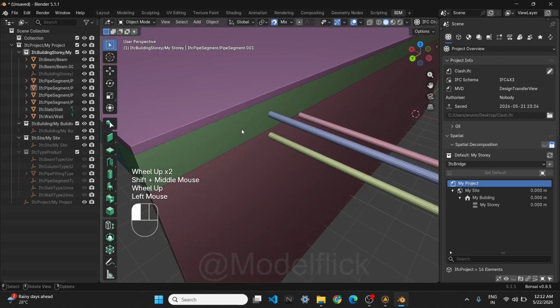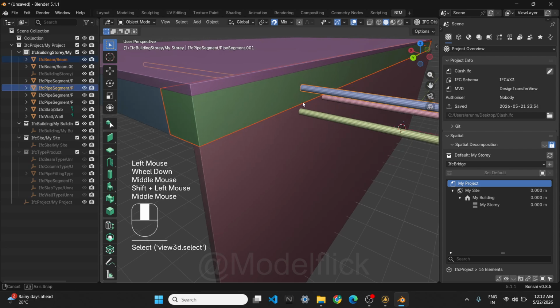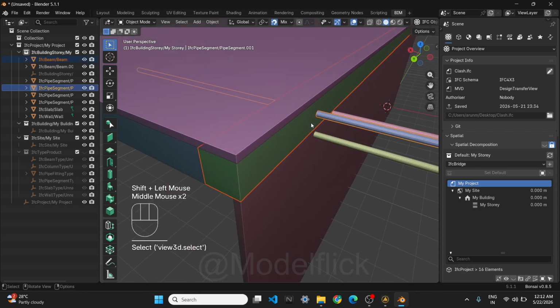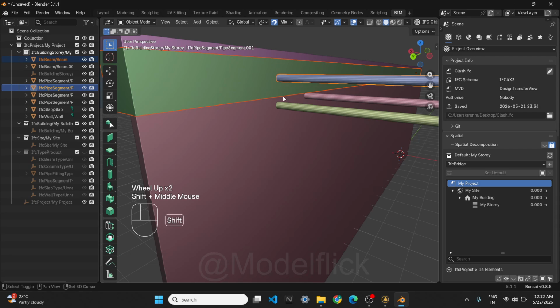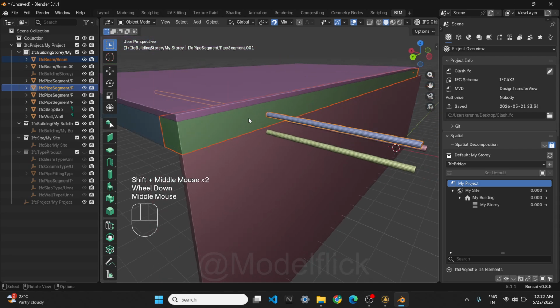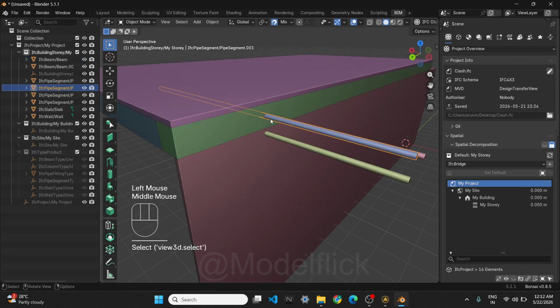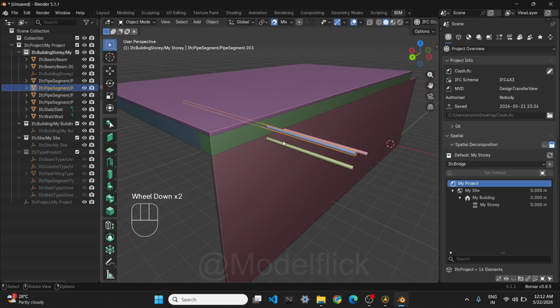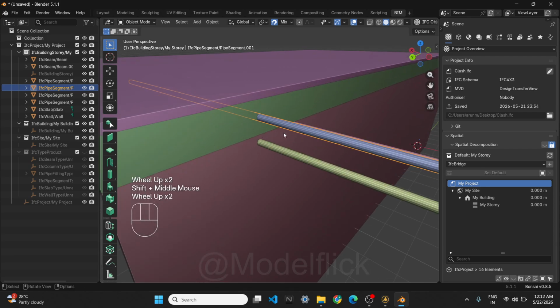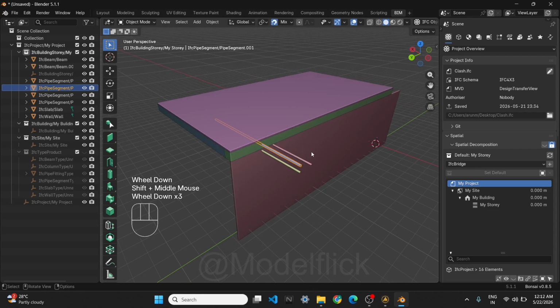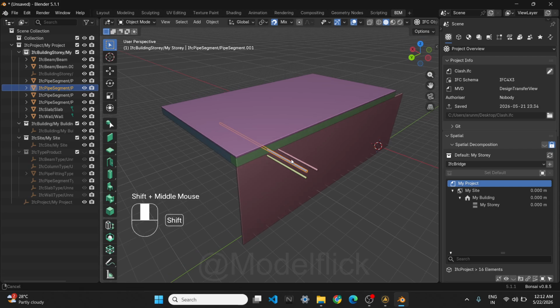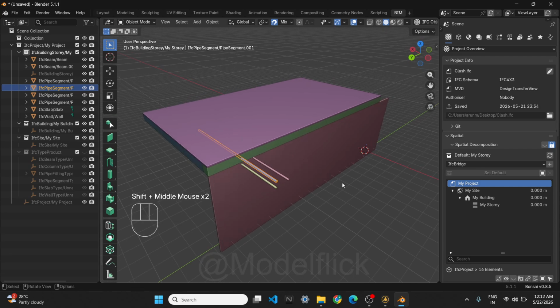For example, here in this beam, a pipe segment is pierced into it. This is not correct modeling, as it may affect the structural strength of this beam. This pipe should not come here, it should come outside of the beam. If this is a small model, we can identify this sort of conflict with manual inspection, but if it's a large model, we can't do it manually. So we must automate the process of detecting these clashes. This is called clash detection in BIM.